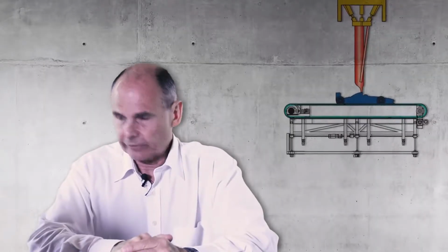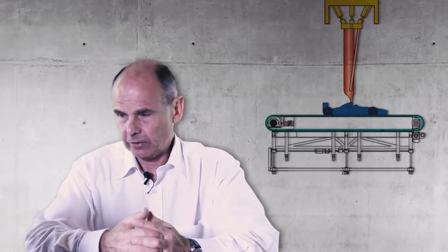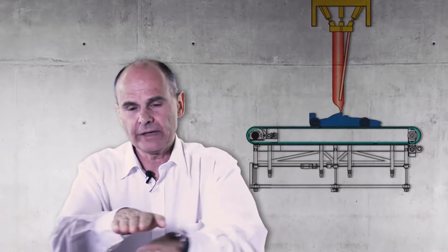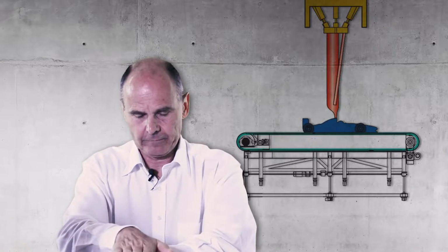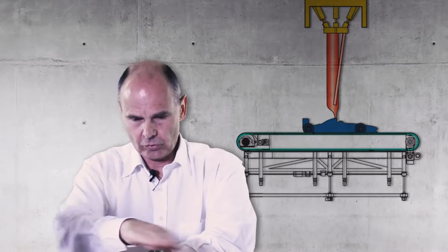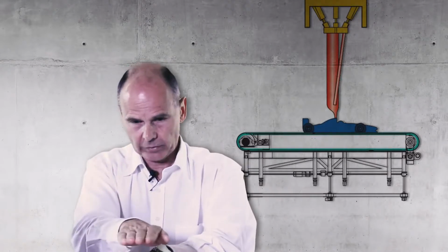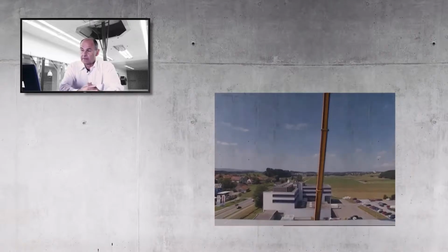However you organise your model, now we use what's called a hexapod, but however you mount your model, you need to be able to move it up and down. You need to be able to yaw the model. You need to be able to roll it. You need to be able to pitch it. Then we have many other degrees of freedom. For example, you can steer the wheels, but that we do from the model.